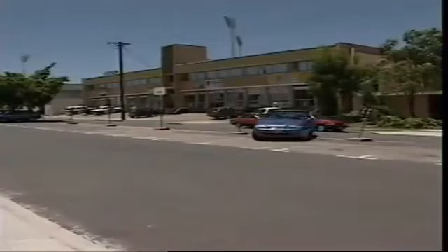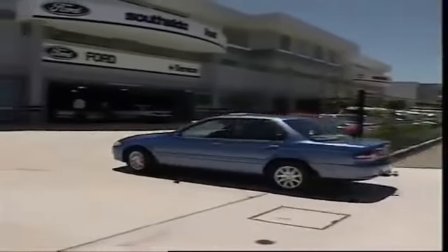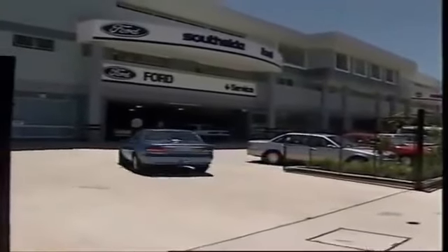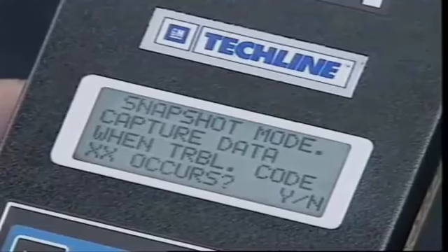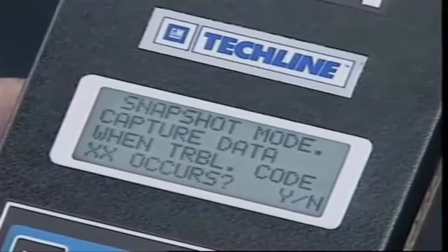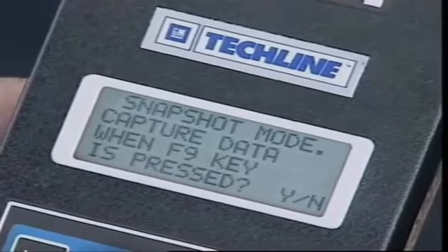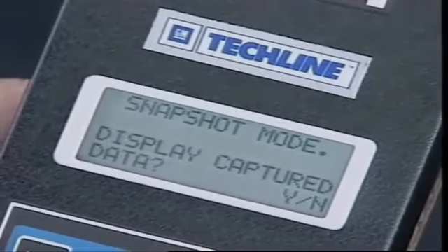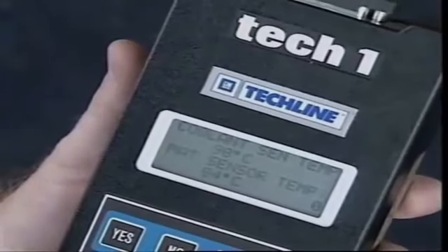In some cases, if the fault is in a major component, the control unit may go to a limp home mode, with a fixed injection duration and ignition setting. The vehicle remains drivable but with reduced performance, allowing it to be driven to a convenient service point. With a data scanning tool, an engine management function can be viewed. All of these functions together are a snapshot of the state of all inputs and outputs at that instant. This data can then be analysed.